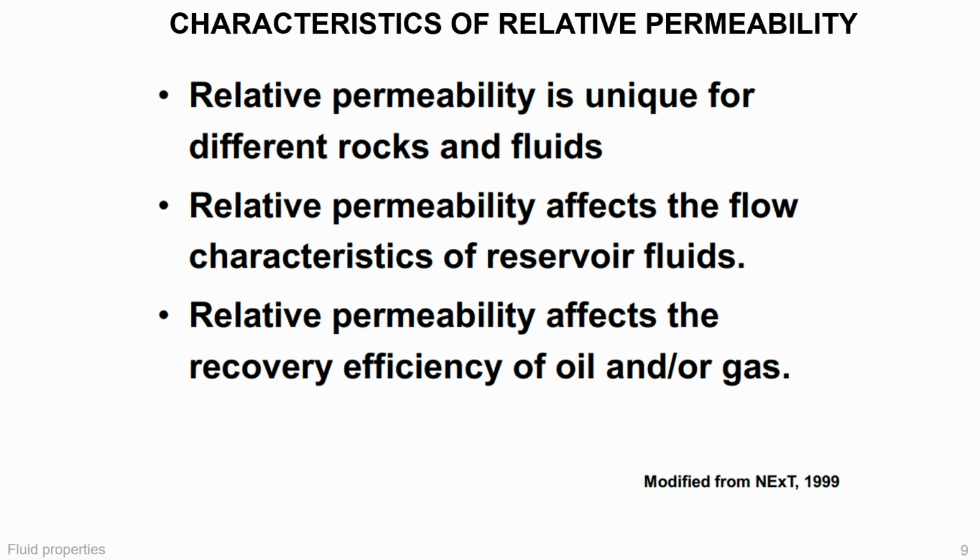This slide usually emphasizes endpoints, Swr, Sor, curve shapes, hysteresis, and the fact that relative permeability functions represent multiphase competition in the pore network. A practical teaching point: if you change wettability from water wet to oil wet, the whole Kr behavior can shift, affecting recovery significantly.